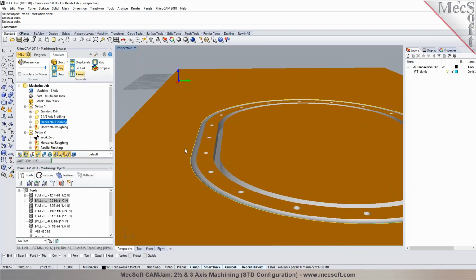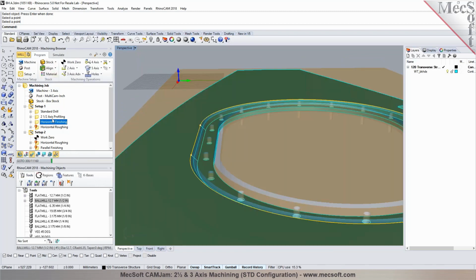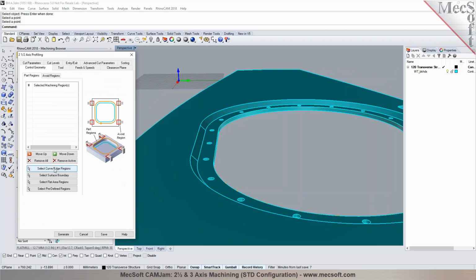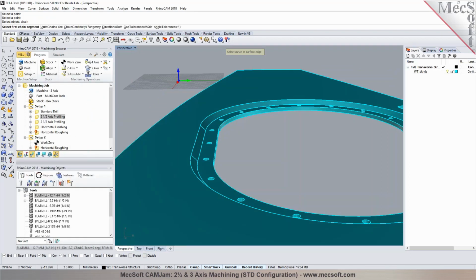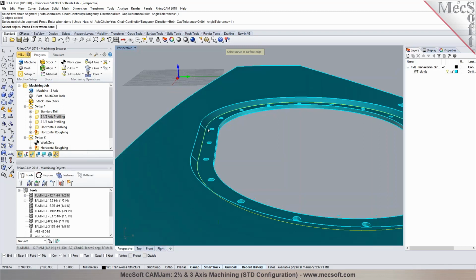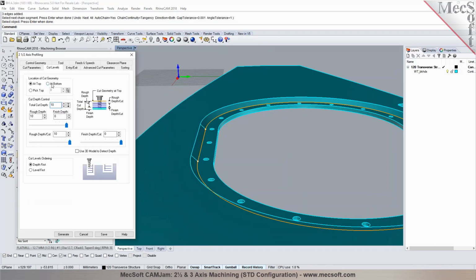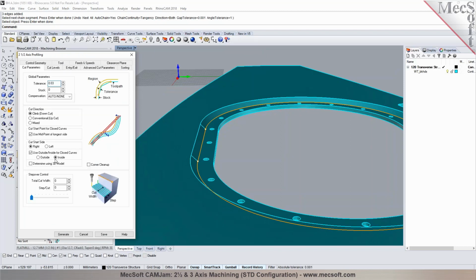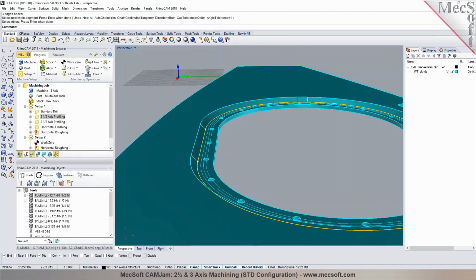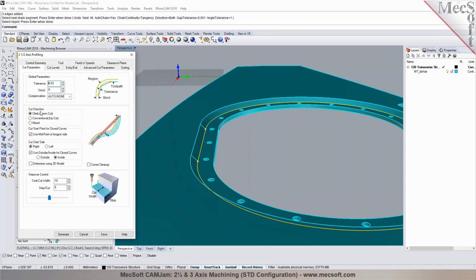Very cool. So before you do this step in here, you could also clear this material out using a profile operation. I can repeat the same profile operation in here and use this select chain command. Pick this chain, so it automatically picks the chain right there. And the cut levels, I could say it's at the bottom. I can do like a 5 or 10 millimeter cutting width in here. So that'll do multiple passes, or I can add a few more extra passes in here.